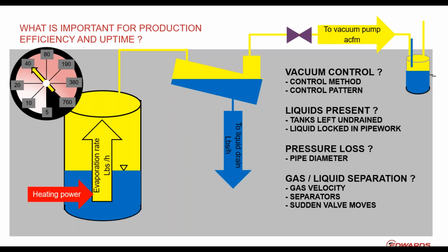Keep in mind, if the vacuum control set point in your reactor is at a point where, just through the liquid states in your reaction and in your system, it is not achievable, because the pressure is not determined by the capacity of your pump, it's determined by the temperature of your liquids. If it's a not achievable process, your control might as well not be present, because the throttle valve will open all the way constantly and cause these effects. So a pressure ramp, as I've shown along the mass flow, just keep that in mind.